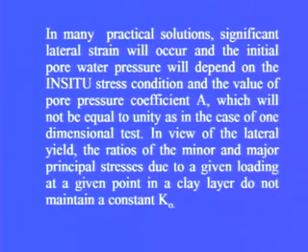In many practical situations, significant lateral strain will occur and the initial pore water pressure will depend on the in situ stress condition and the value of pore pressure coefficient A, which will not be equal to unity as in the case of the 1-dimensional test. In view of the lateral yield, the ratios of the minor and major principal stresses due to a given loading at a given point in a clay layer do not maintain a constant K naught.